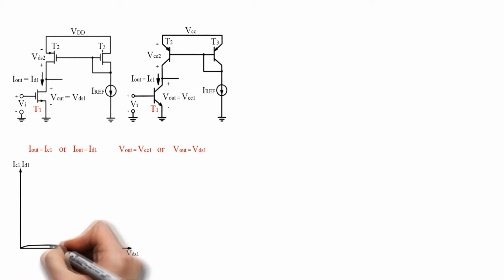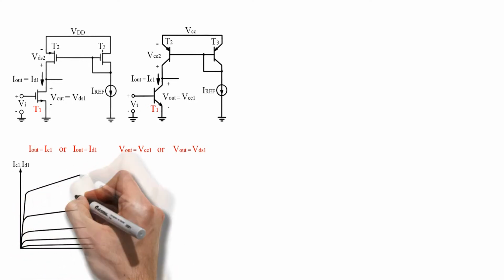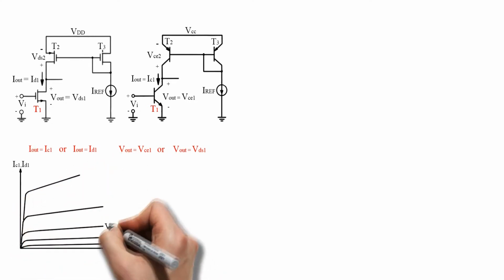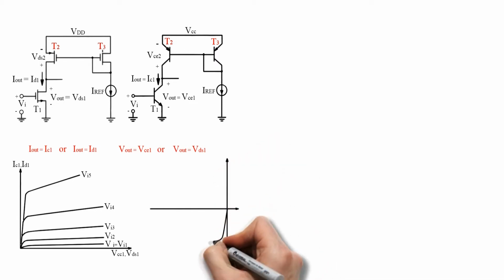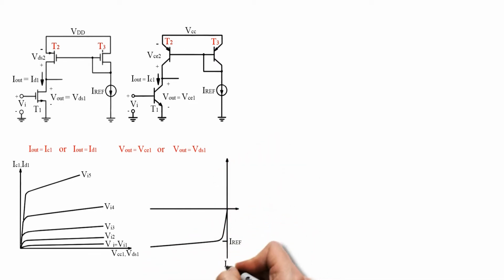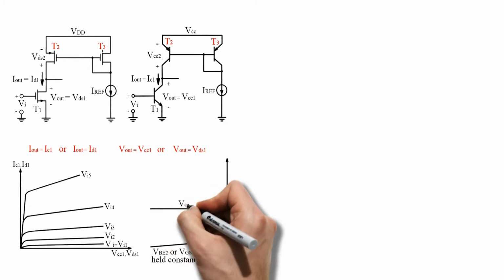The input voltage is the parameter that determines the particular curve in the family of output characteristics under consideration at any point, as shown in Figure 4.17a. In contrast, the base-emitter or gate-source voltage of the load transistor T2 is fixed by diode-connected transistor T3. Therefore, only one curve in the family of output I–V characteristics needs to be considered for the load transistor, as shown in Figure 4.17b.